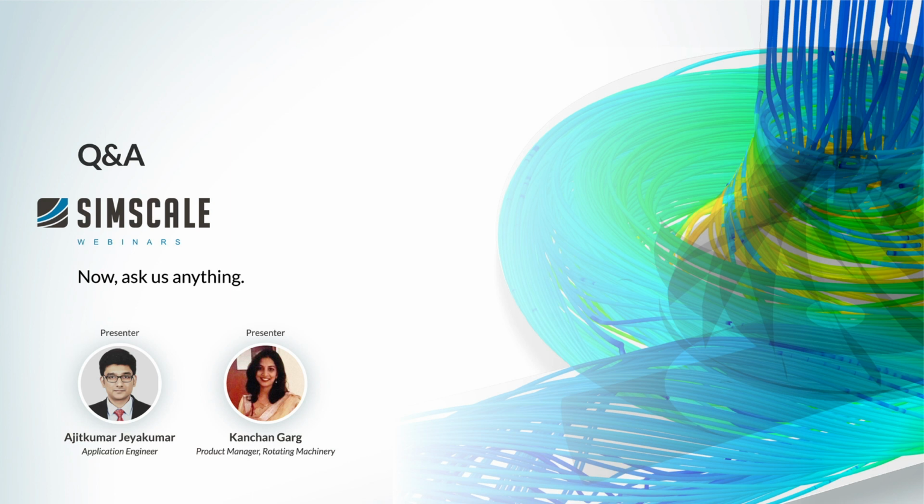What different refinement zones can be given for mesh refinement? Okay, I can take that question. With respect to subsonic, right now you can create geometry primitives that are cylindrical or box in shape. And it could be around your impeller or rotor or behind the rotor if you wanted to resolve the wake. But at the moment, we support box and cylindrical geometry shapes.